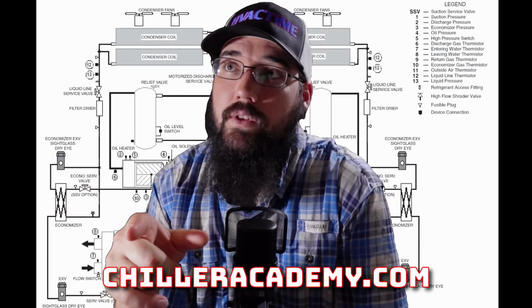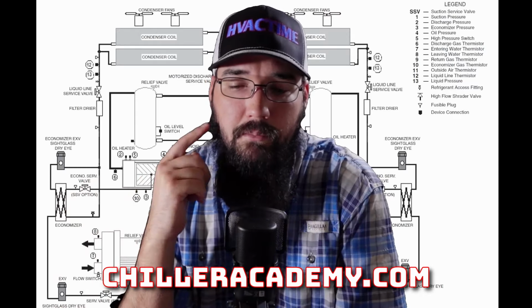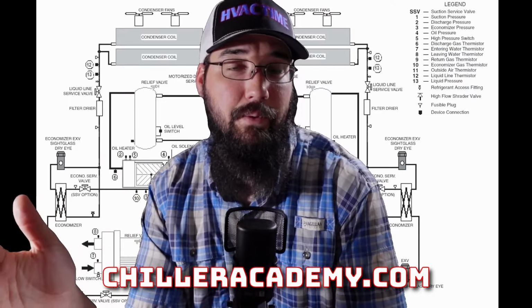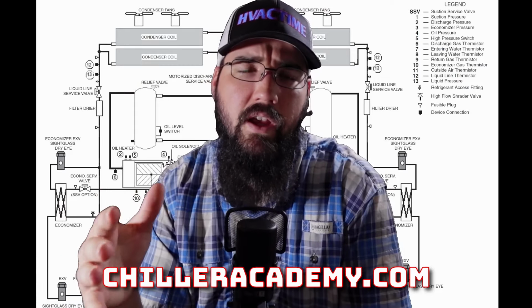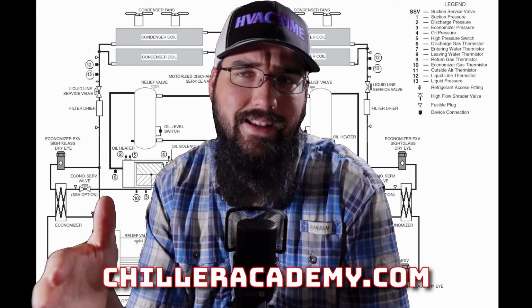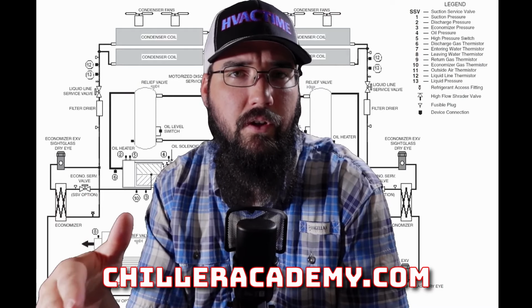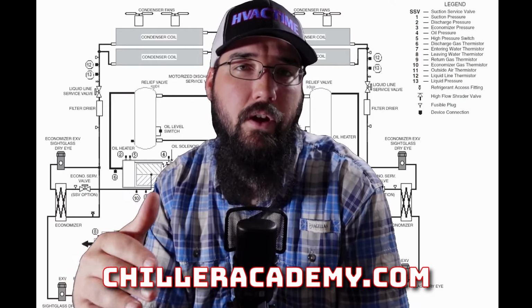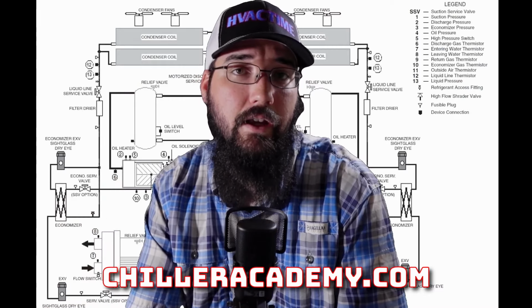So I'll use the Trane RTAA specifically, for example. I remember this: whatever the evaporator pressure was, the condenser had to maintain 70 psi above that. And that's about right, because with a lot of screws, you really need at least about 60 to 70 psi before they really run smoothly. And most of them run even better closer to 80 to 90 psi.